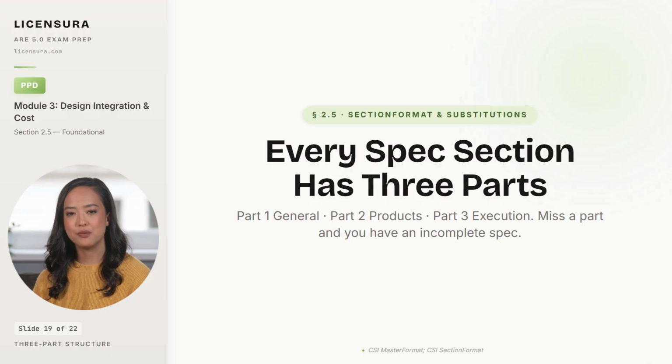Here is the section format rule you must know on site. Every specification section follows the same 3-part structure, regardless of which master format division it lives in. Part 1 is general, administrative and procedural requirements for the section, including submittals, quality assurance, delivery and storage, and warranties.